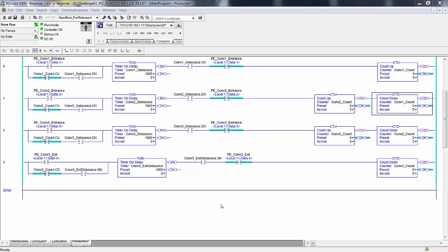So we'll say the first station, it rolls out a piece of wax paper onto a platen, and the next station, it folds it around a block of aluminum. We'll call it a dummy interior, or the shape of the interior of the carton where the cereal is going to go. It wrapped the wax paper around that and sealed it. And then in the next station, it started a piece of paperboard that would then wrap around that. And then the next station, it finished wrapping around that. And the next station, it closed up all but the top of the breakfast cereal box.